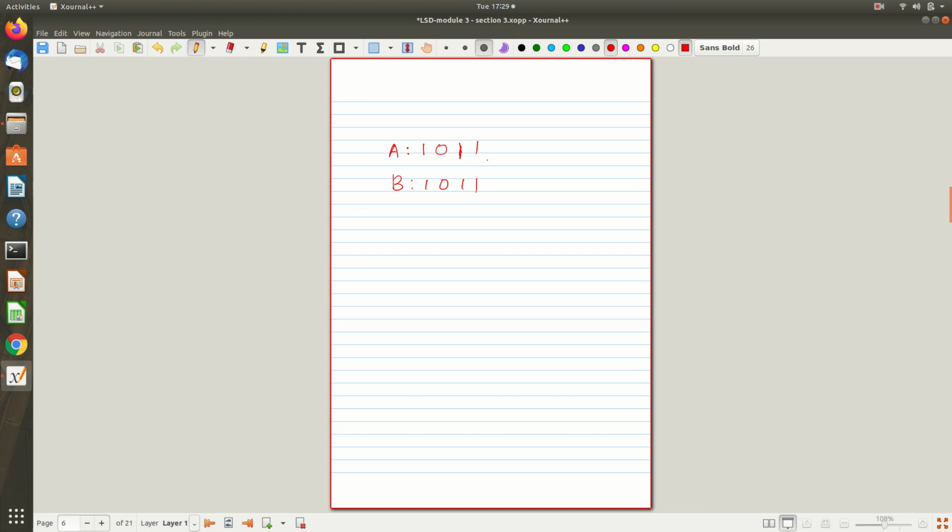You know that both are the same, so now I need to implement this using some smart logic, right? You know that these two numbers are the same, so I just want to implement it logically. So first, without depending on the truth table and all, I'm just comparing each bit side by side. If all the bits are the same, I can say that the equality is satisfied. So when I'm looking at the least significant bit, you can see that this is 1 and 1, right?